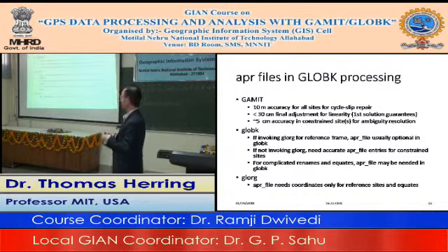And we'll see that when we look at some of the utility programs like TSFit, again for large data sets, we now have a much cleaner way of creating these APR files. GLOBK, the APR file, needs to have accurate coordinates for the reference frame sites. Those are the ones that have to be accurate, and for anything where you're doing equates on parameters as you go across.